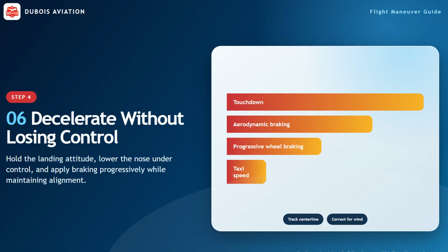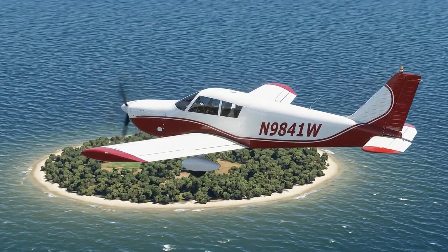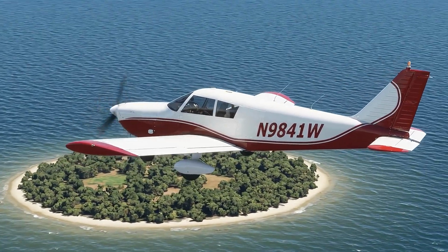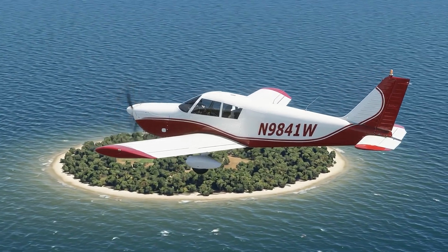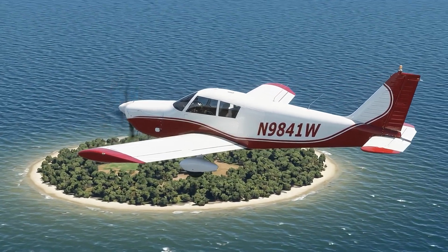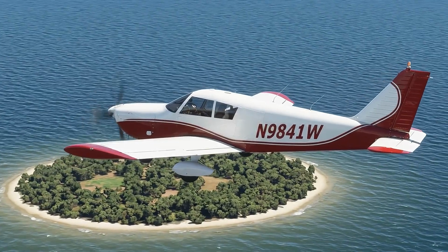Apply wheel brakes progressively, keeping the airplane straight and adjusting aileron for the wind. Maximum braking does not mean locking a wheel. Use the amount of braking the surface can support, and continue flying the airplane until clear of the runway.